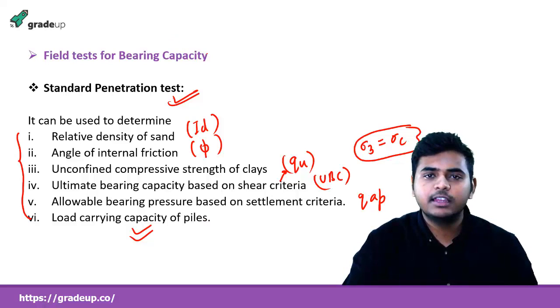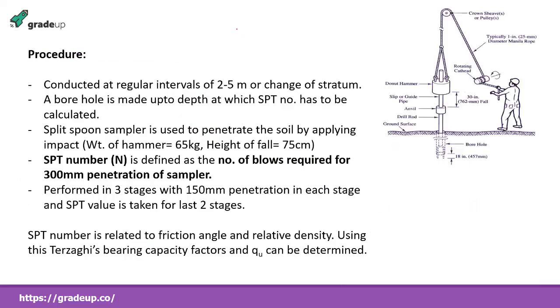This test is generally asked in the different competitive exams. You have some correction factors as well. You have to keep in mind all those. So let's see the procedure. This is actually the whole apparatus of standard penetration test. It is conducted at regular intervals of 2 to 5 meter or when stratum is changing.